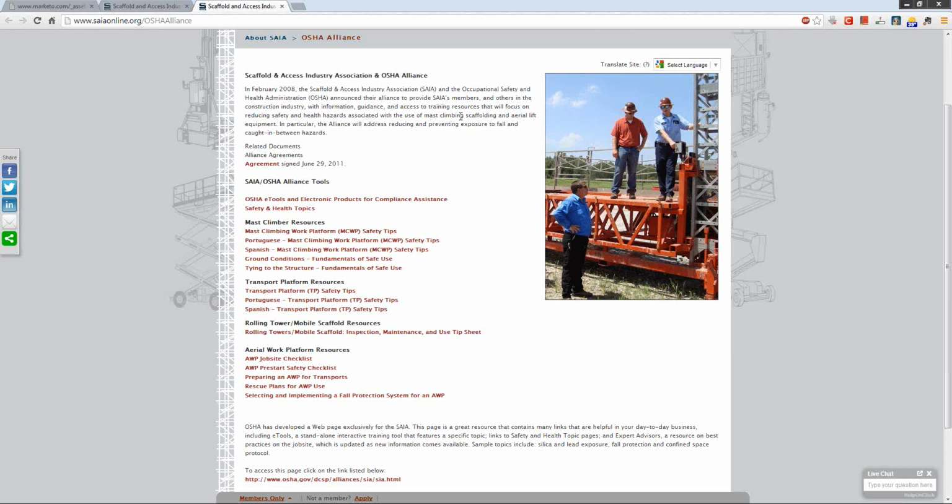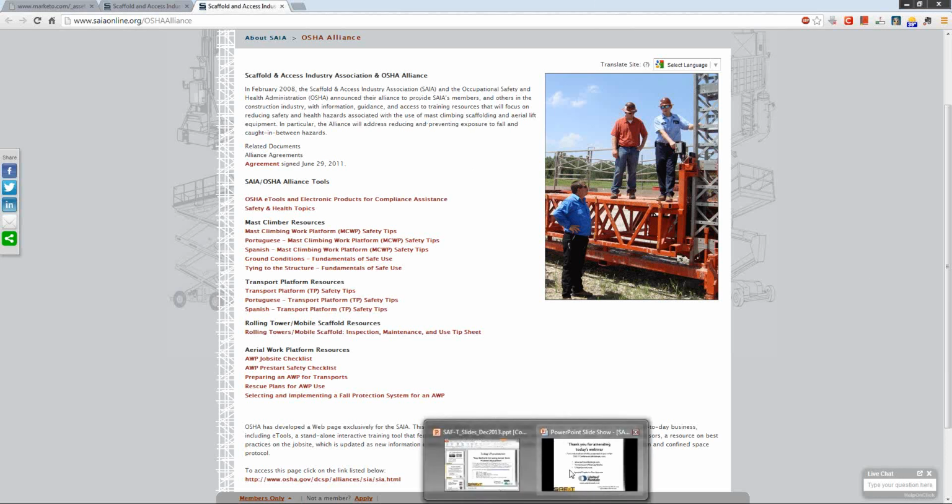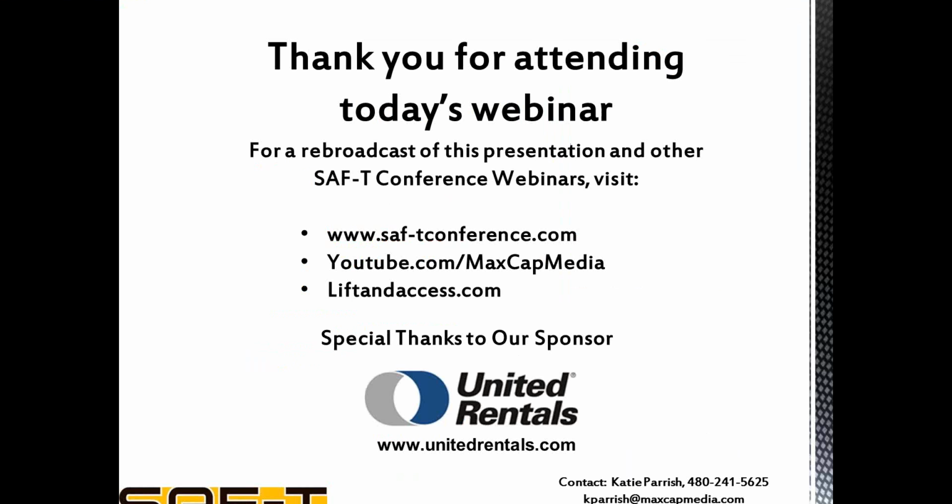Well, the way to answer that question is I'm going to start with the standards, and the standards say entering and leaving an elevated platform, if permitted by the manufacturer, follow their rules and instructions. Some manufacturers have publicized information, and some do not. So it depends on the manufacturer if you're following ANSI. Now that you're outside the platform, you fall under Subpart M, fall protection, and 100% tie-off must be achieved.